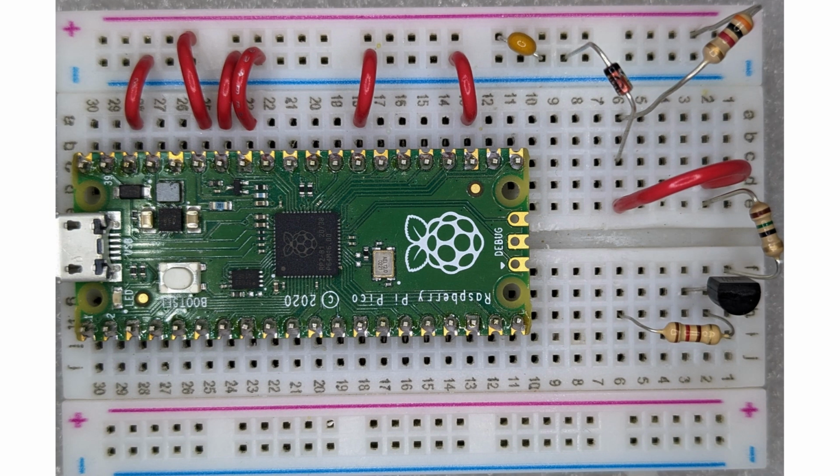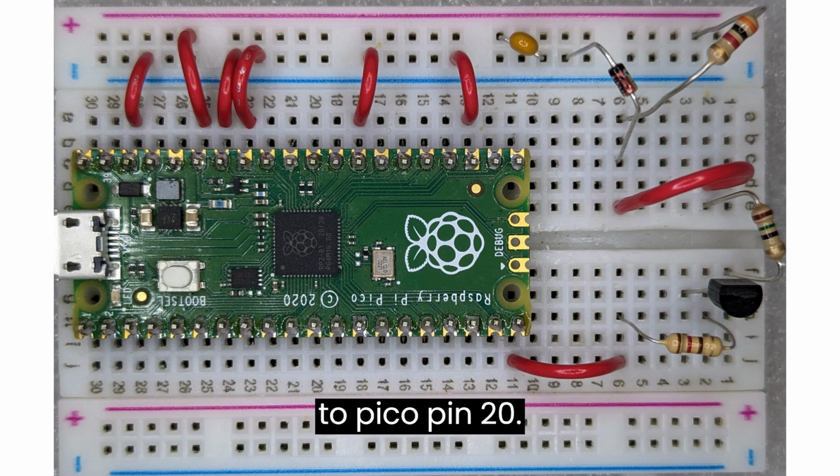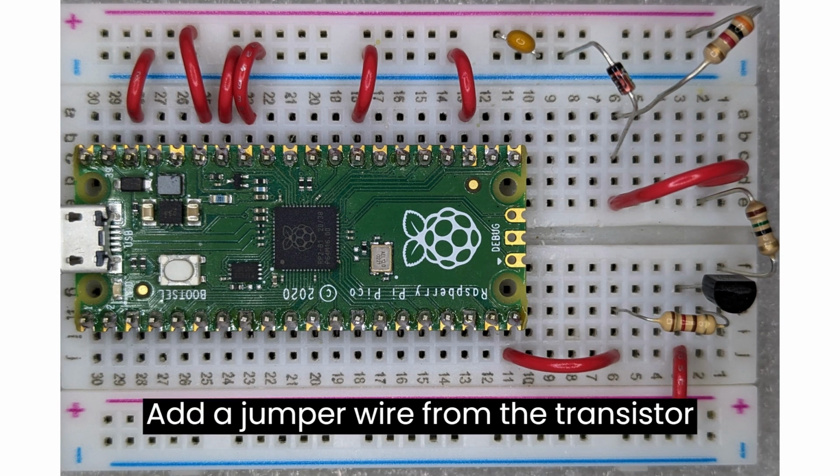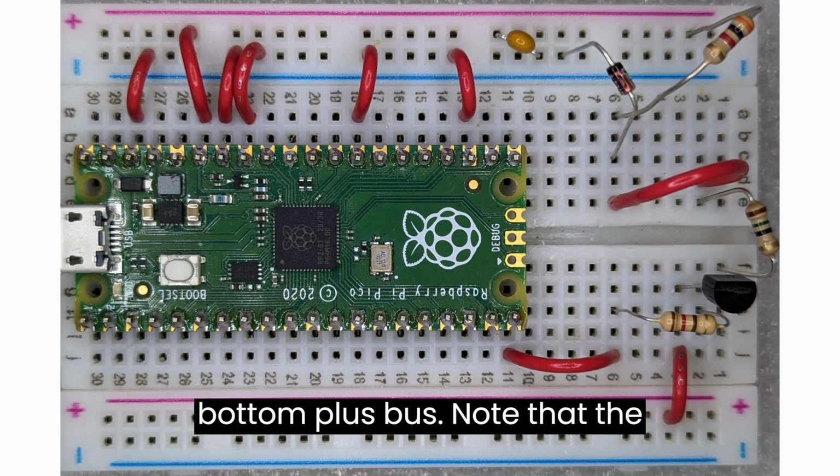Insert a 120 ohm resistor from the transistor base at bus 2H to bus 6H. Add a jumper wire from bus pin 6J to Pico pin 20. Add a jumper wire from the transistor collector at bus 3J to the bottom plus bus.